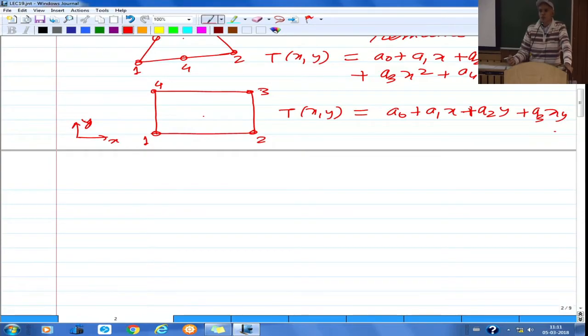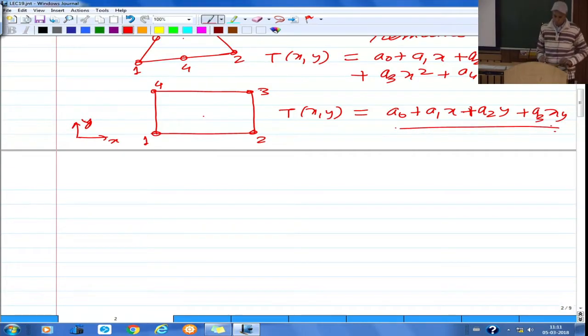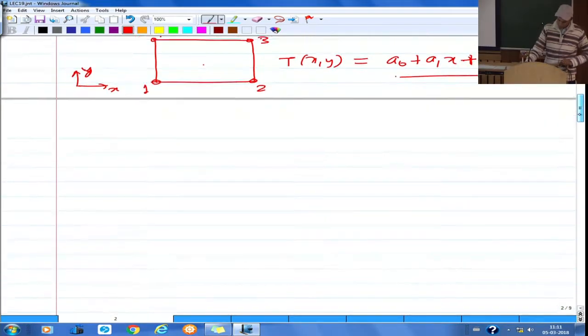But when you formulate a finite element, of course, you can always formulate a problem for a specific case wherein the variable is varying with a higher degree variation along one direction and with a lower degree variation along the other direction, then you can formulate that kind of element. But for a general case, it should be geometrically invariant. So this is what you will take as the interpolation here for the 4 noded quadrilateral element.